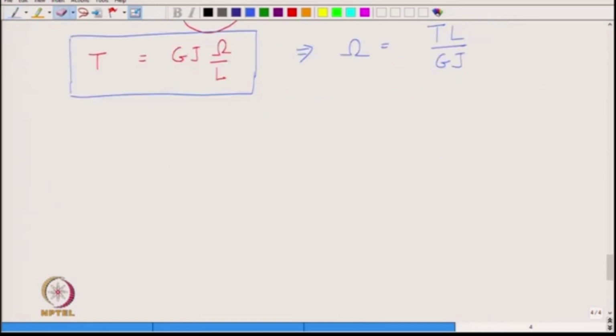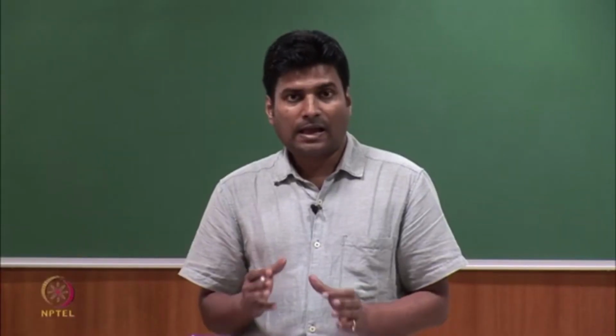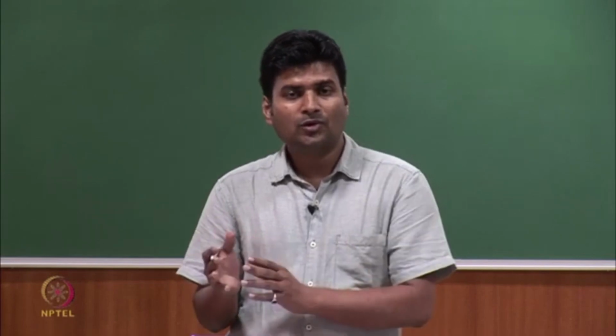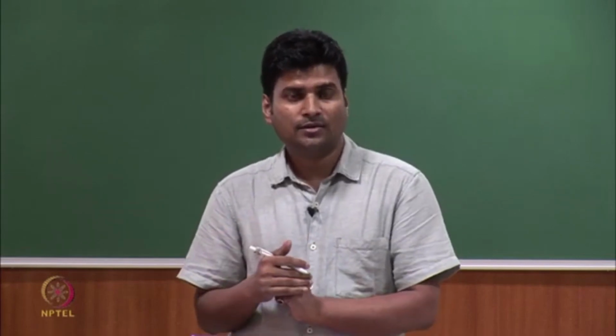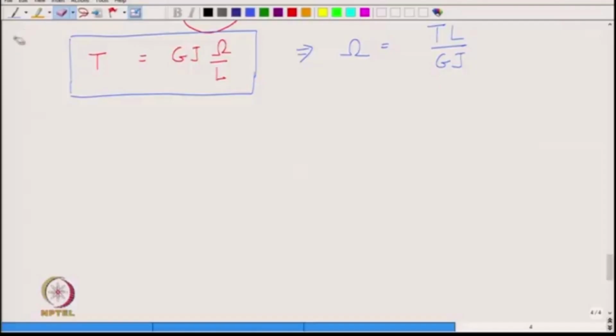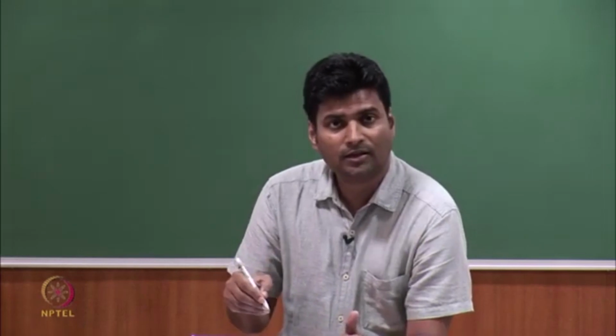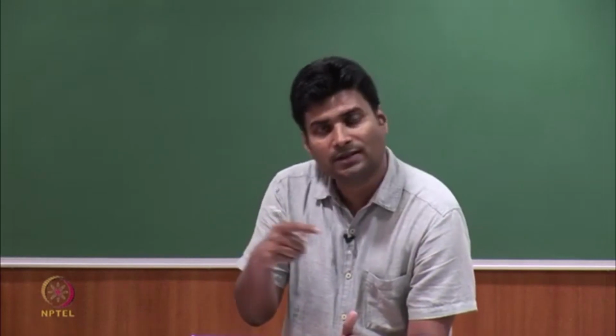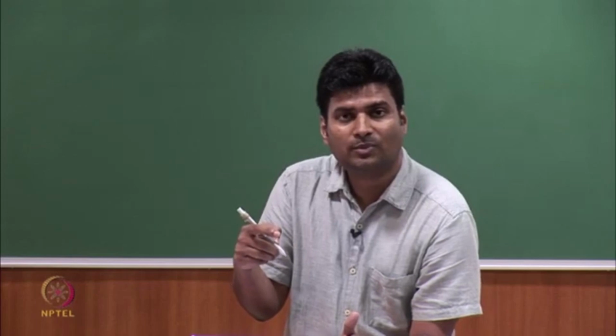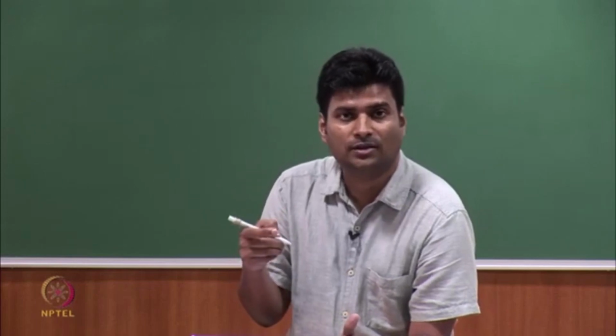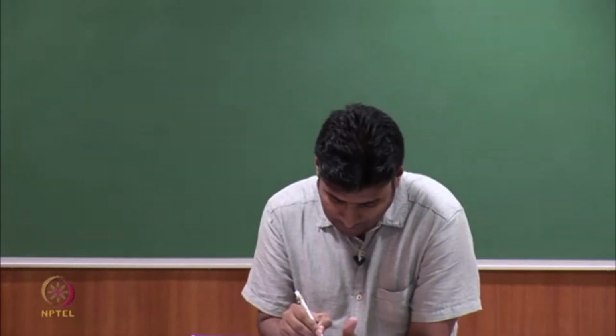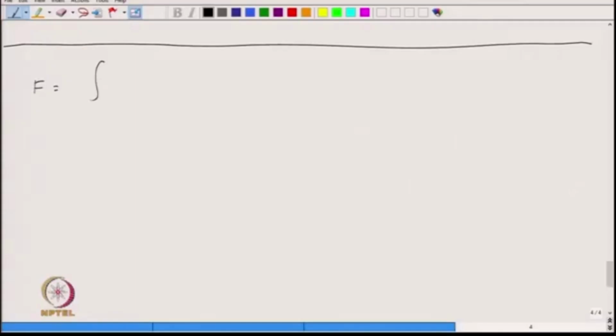Okay, we still have to get epsilon, right, and I guess it should be related to the axial force applied, is not it. So, let us try to get epsilon in terms of the axial force. So, we again have the cross section, and the axial force is the force in the axial direction, so it should simply be integration of sigma zz, is not it. So, the force F is the integration over the cross section of sigma zz times dA.